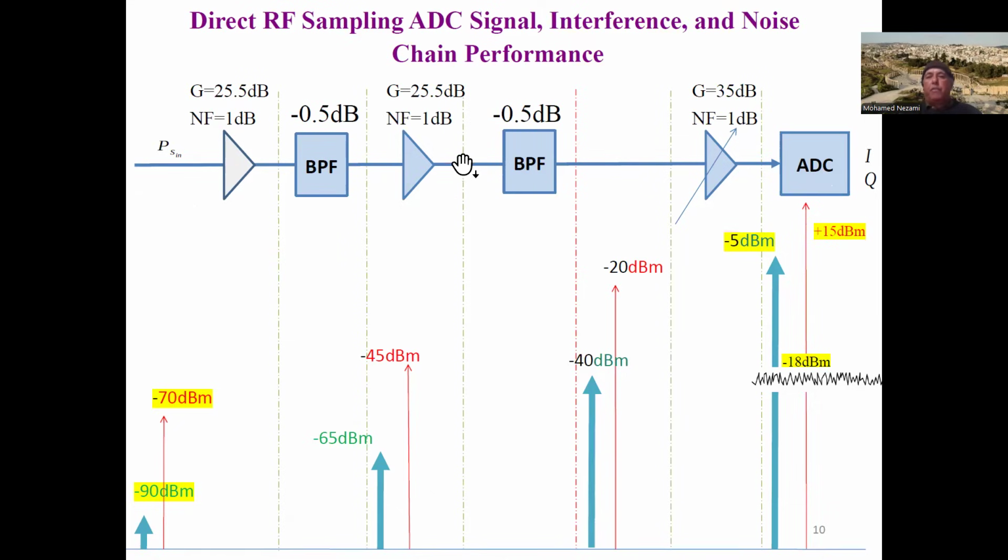If I had frequency translation, as soon as I mix with an LO, this here will move away from the desired signal, and I will be able to reject it in the IF amplifiers, IF filters, ceramic filters at the IF stages or LC filters.